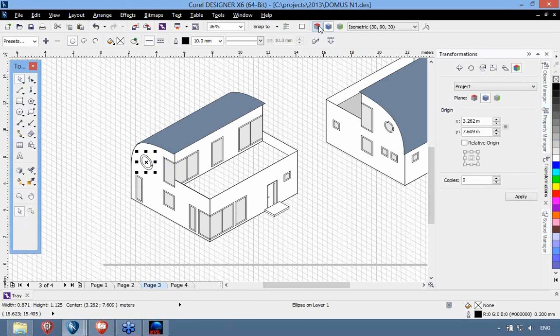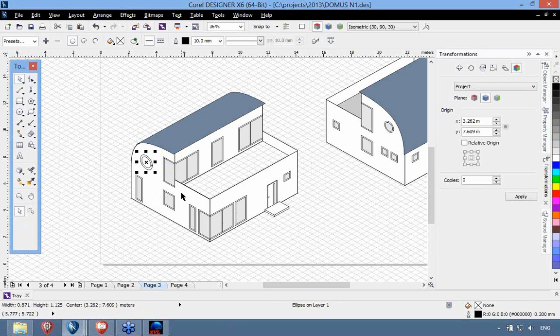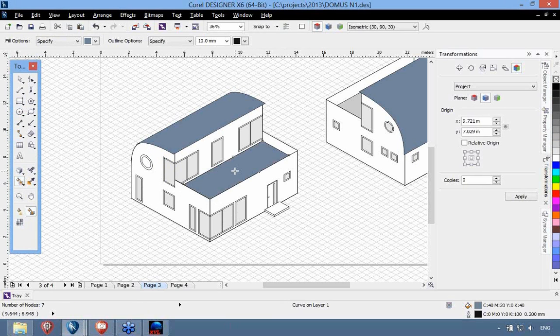Okay. And what I want to do as well is to fill this area, and let me do that with the Smart Fill tool, so that recognizes the next edges. Don't be confused by the grid. This is not real objects, that's just guidelines that help you understand the drawing plane you're in.